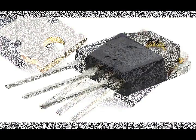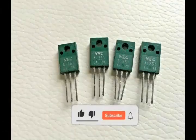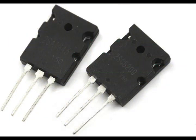Transistors used in high-power amplifiers and power supplies are called power transistors. There are transistors of this type in the form of NPN, PNP, and Darlington transistors. Their collector current is between 1 and 100 amperes.